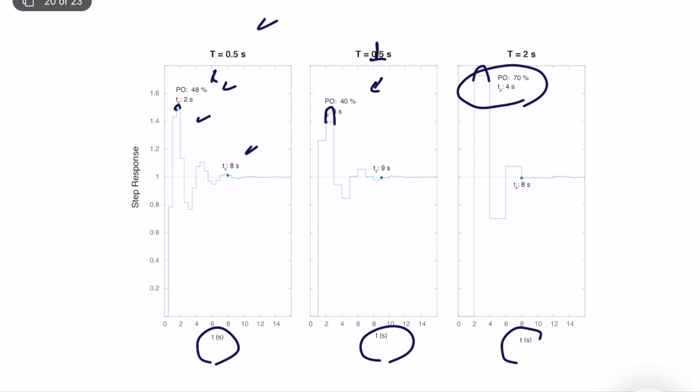Still, it is obvious that the worst overshoot performance is happening with the largest sampling time, or lowest sampling frequency. So in general, it's hard to compare close numbers in discrete time systems, because we technically slightly ignore what's happening between two sampling times.